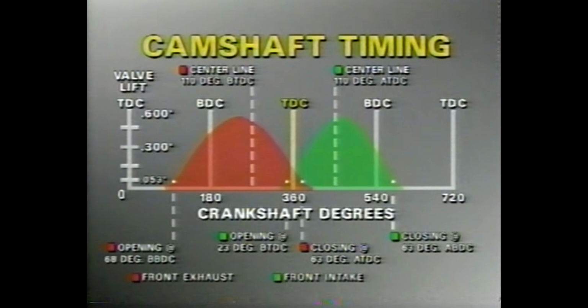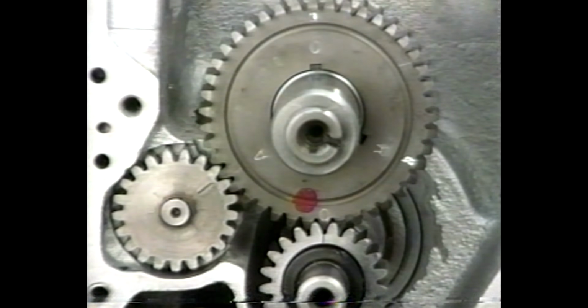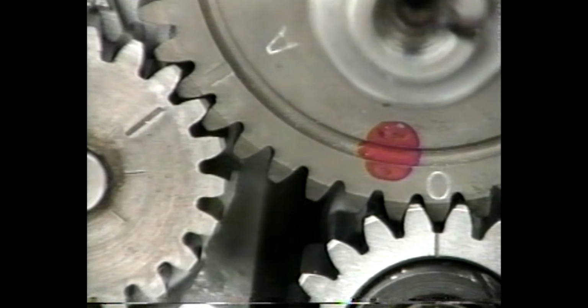If we have to advance or retard our cam by more than 4 degrees to get desired performance from our engine, then we have selected the wrong cam for this engine. Our only recourse is to select another camshaft that is better suited to our requirements. Under no circumstance should a rough trial and error method be used to find the correct cam timing. Rotating the cam by just 1 tooth in either direction translates into an adjustment of approximately 18 degrees, which is far too great a change and may cause major problems.